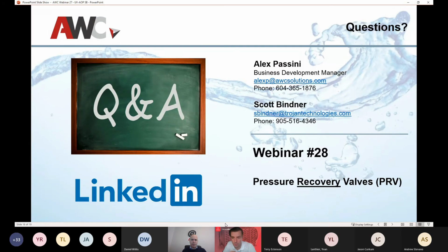That's an excellent question. For most applications, we are using the 254 low pressure lamp emission spectrum, basically at 254. Medium pressure lamps, which have a polychromatic spectrum that emit at various wavelengths, can also be used. But I mentioned that nitrate absorbs below 240, and medium pressure lamps can emit at 240. So nitrate has much more of an impact on medium pressure UV as opposed to low pressure UV.